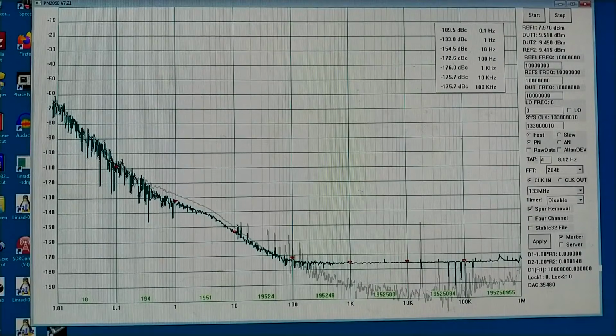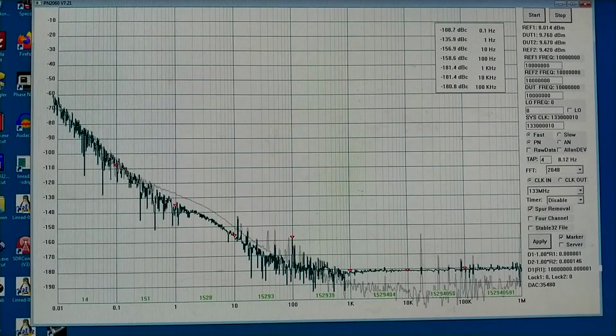So I opened the box to fix the mechanics for making the box less sensitive to vibrations. Then I discovered something. There were oscillations at about 500 megahertz. Not very visible on the oscilloscope, which is limited much lower than that, but I could see it. So I added some capacitors and some other little things, and now I have this situation.